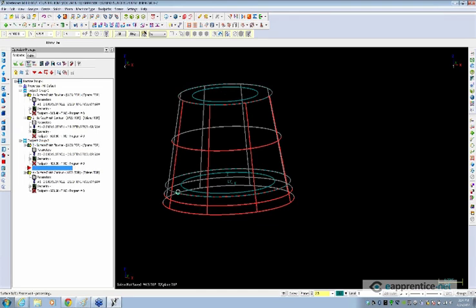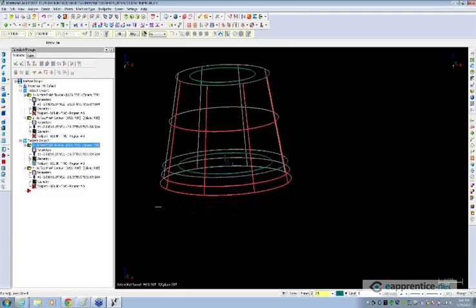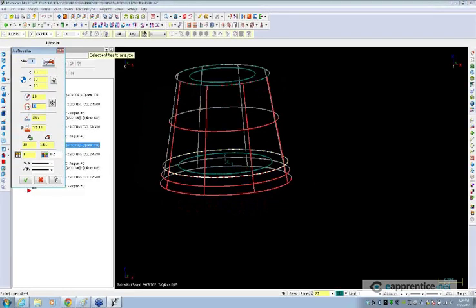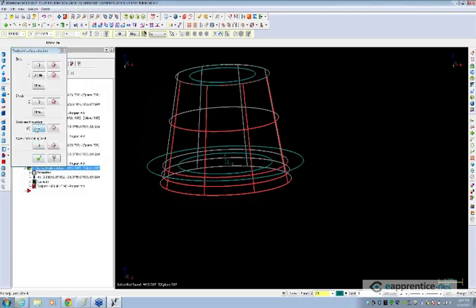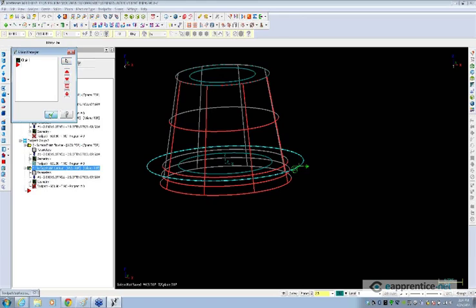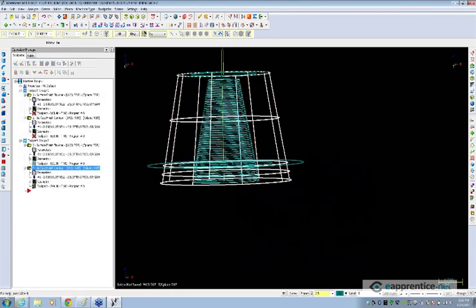Right now, if I did my finished contour, it would still be restricted by my boundary, so I'd also have to take this arc and offset it. So if I click on that arc, right now it's a 4-inch diameter. Let me make it a 5-inch diameter. It's still going to remain associated as my containment boundary. Mastercam's smart like that. So we'll go ahead and regenerate both those toolpaths that we just created, and we should get motion that now does go down, in this case another additional 1/2 inch.